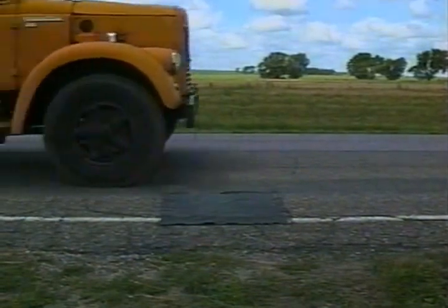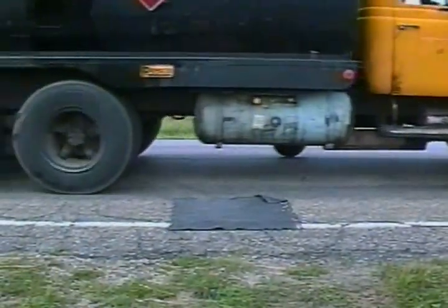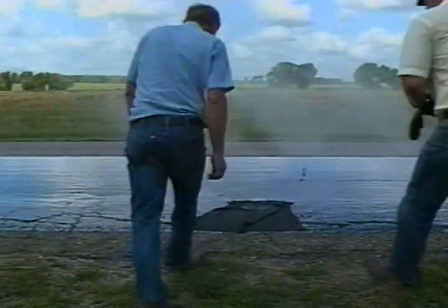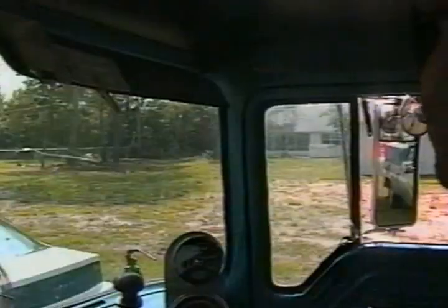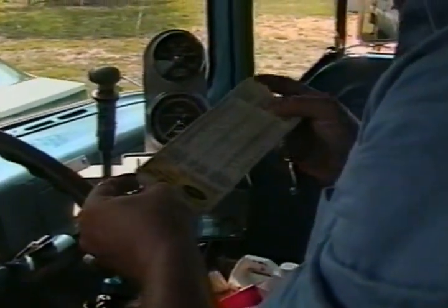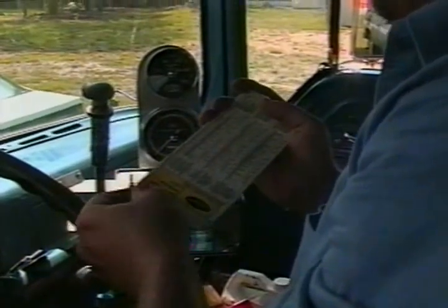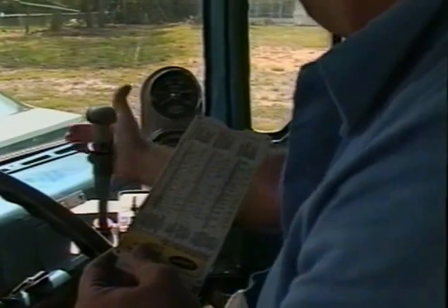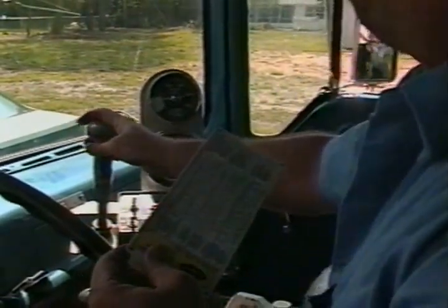The oil application rate can be checked in the same basic way, using a pan or a piece of non-woven geotextile material, 1 square meter in size, to catch and retain the oil sprayed by the distributor, and then weighing the collected oil to calculate the rate in liters per square meter. In both cases, compare the results with the target application rates and make adjustments to the equipment as necessary. When the rates check out, you can begin chip sealing.